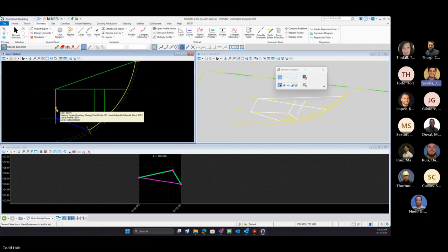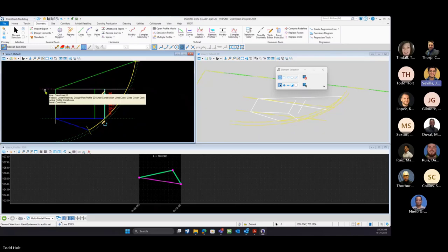So in reality, that line is going to be a little bit above existing ground, or maybe below. Yeah. Because if you're just tying to existing, you're not going to get that. Although it can be maximum 1 to 12 or 8.3% or less. If it is flatter than that, then that's fine. Okay.